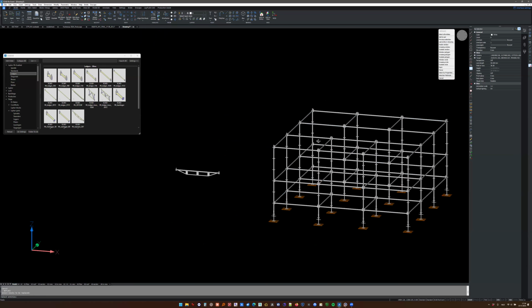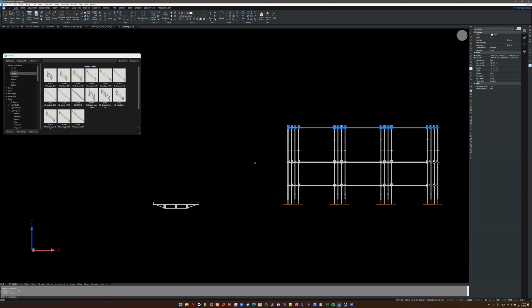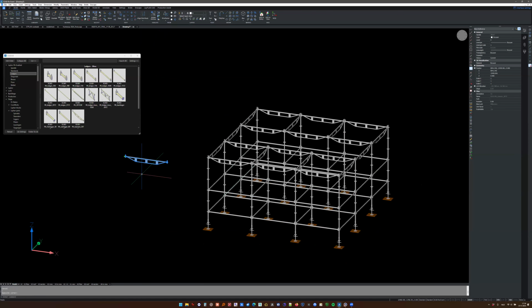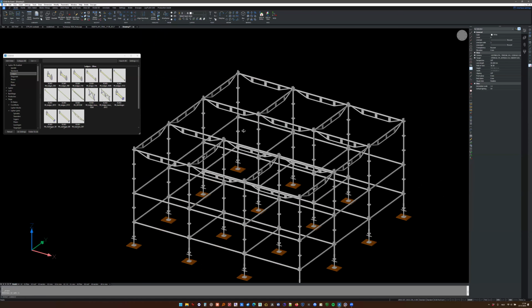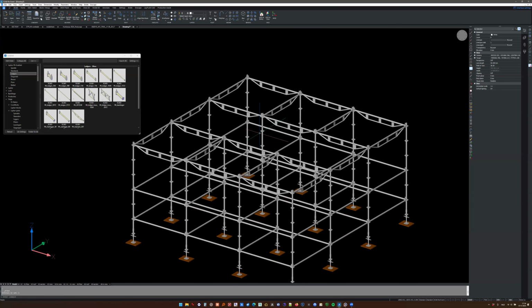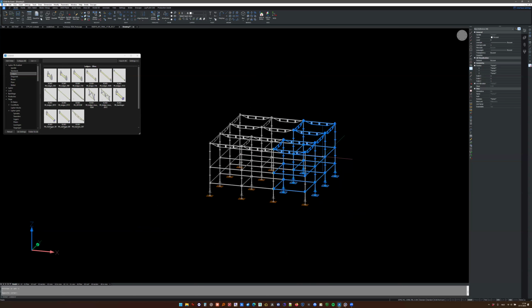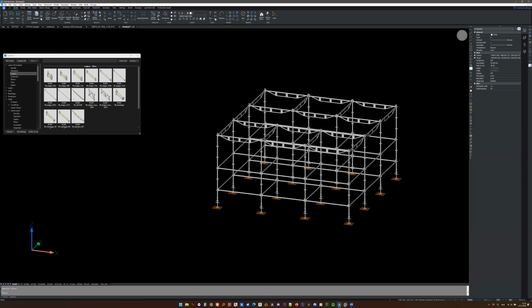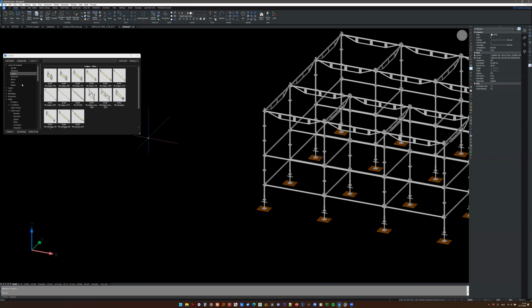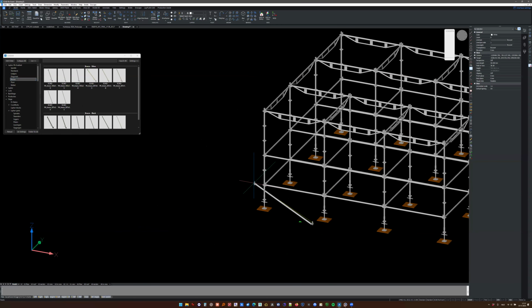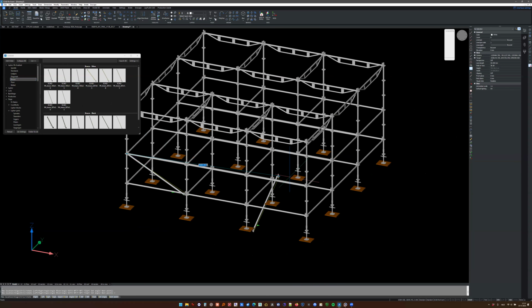I select the objects I want to replace. Normally I pre-select them, and then I select the objects with which I want to replace them. So if I need to change something in the drawing, I can do it really fast. There are also some filters that I can select to partially select only a certain kind of ledges, to build this really fast. When I go to the next and work with braces, I can also easily rotate the object by clicking, and then copying is the same way I did before.